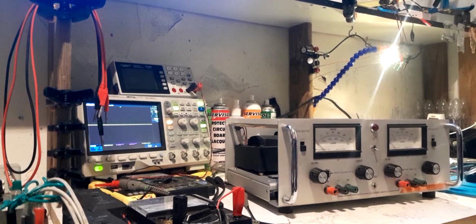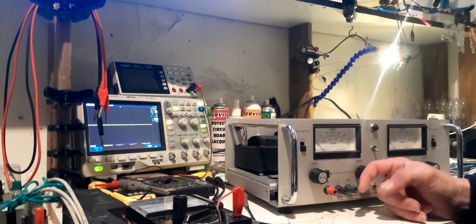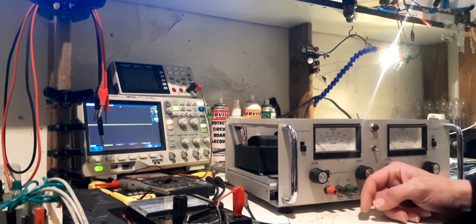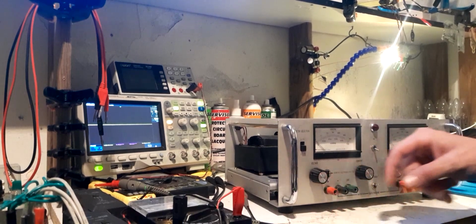Anyway, it just makes more sense. They're going to be able to maintain more accuracy with any fluctuations with that small current going to them. It's just going to be better. I'm not talking about the cathode current, I'm talking about the reference current, because the thing you've got to remember here is you've got a dropper resistor coming in. The pots that you use to set the reference voltage, if you have that too low in resistance, to get more current to the reference pin, you're going to pull down the voltage and current from the dropper resistor to ground,